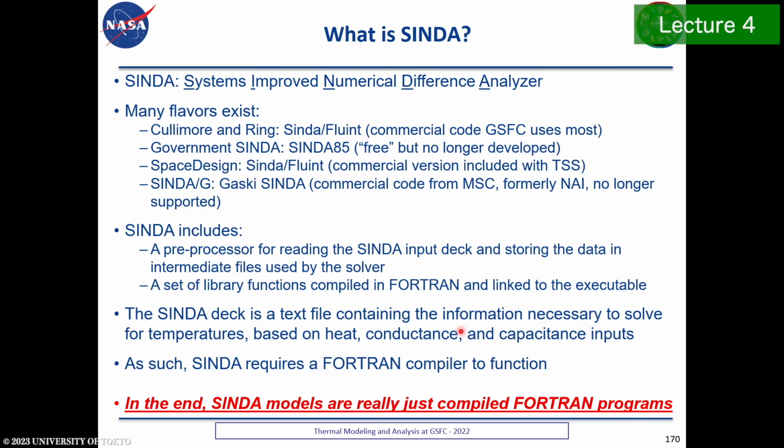It contains all the information you need to solve for temperatures. But it does require a Fortran compiler or some other kind of compiler. If somebody wanted to rewrite CINDA, they could do it in C or MATLAB. But in the end, it's a collection of functions, calling those functions, and data that defines the physics of the problem. In the end, CINDA is really just a compiled Fortran program.